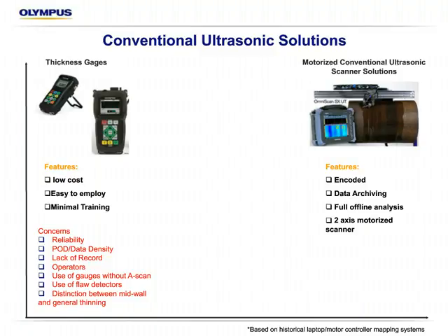So at a minimum, if we can make any recommendation with thickness gauges, if you're looking for corrosion or you're in the in-service market, it's that you at least get a quality thickness gauge with an A-scan or waveform presentation, so it gives the operator a little bit more to go on to make the correct distinction. There's also a big trend to use flaw detectors in lieu of dedicated thickness gauges, or something you might go out and do a shear wave examination with, and then you just put a 0-degree transducer on it and try to take precision or accurate thickness measurements.